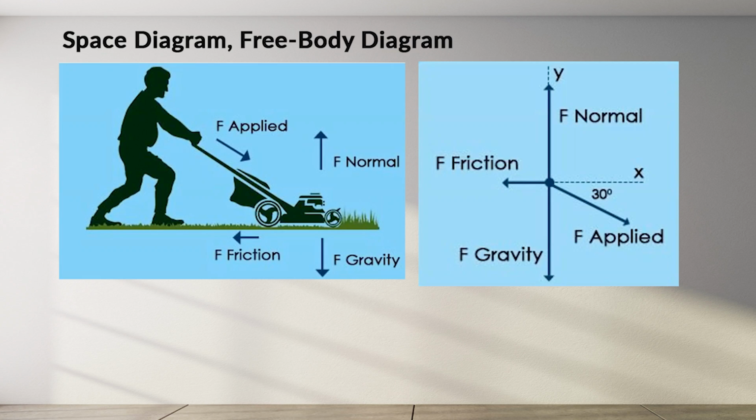Among the forces to be shown will be the weight. The weight of the body acts through a point called the center of gravity of the body, which is directed from the center of gravity downward toward the center of the Earth. For a uniform body, the center of gravity is the geometric center of the body. For non-uniform bodies, the center of gravity's location is usually designated as CG, or by the symbol of a circle divided up into 4 sections with the upper left and lower right sections shaded in.